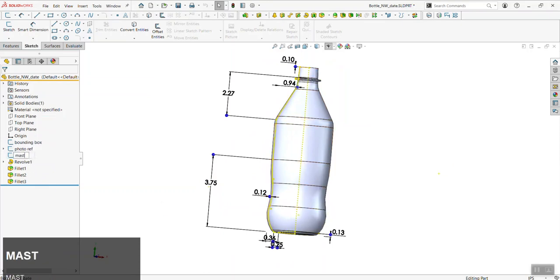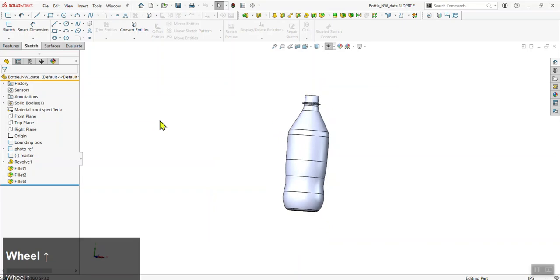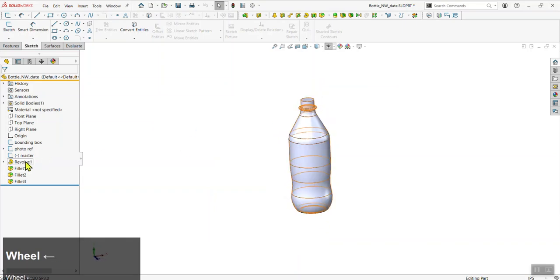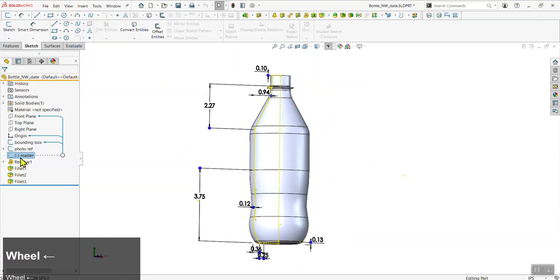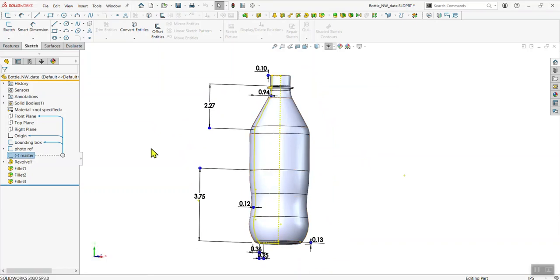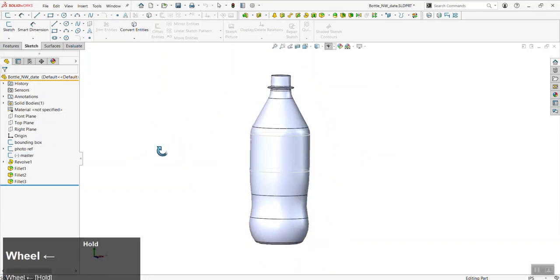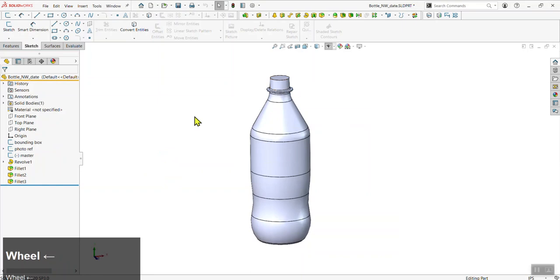This is what drives the form of the model and is a sort of SOLIDWORKS building technique to keep your file organized and robust, having your features point to one sketch essentially. Once you have that done, we're going to go ahead and make the cap.